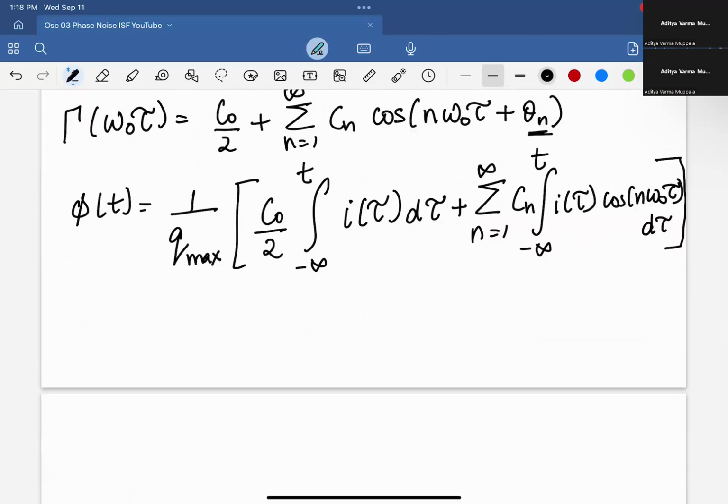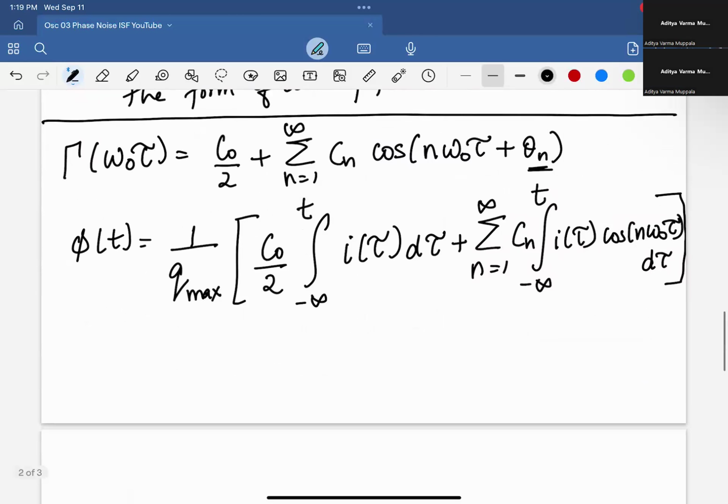So today what we'll do is use this model essentially to take different values of I. So we'll look at, okay, if I have a certain I, some current, starting with a sinusoidal current, how that can produce the phase noise skirt, right? Like what is the mechanism behind how that translates to this? And then from this through the nonlinear function into the voltage at the end, right?